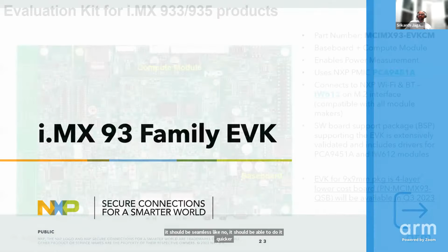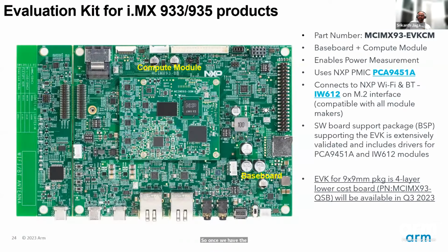So once we have the SoC from NXP, we offer evaluation kits to evaluate the product, and we enable customers to run their application and measure performance or measure power. So this is the evaluation kit that we have for the i.MX93. We have a base board that has a lot of these connectors, and then on top we have a compute module that has the i.MX93 SoC along with NXP PMIC, which is the power generation module, and also the eMMC and then DDR.